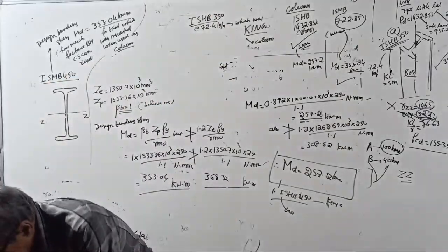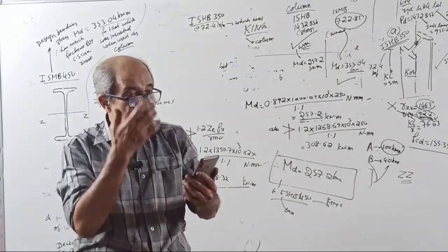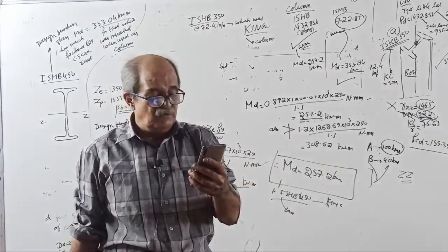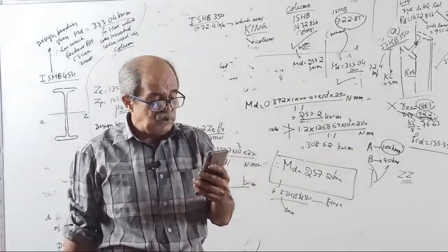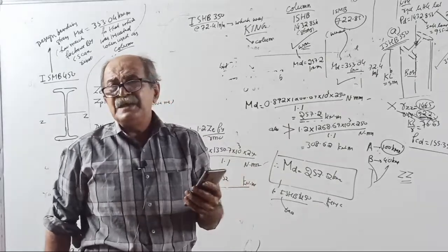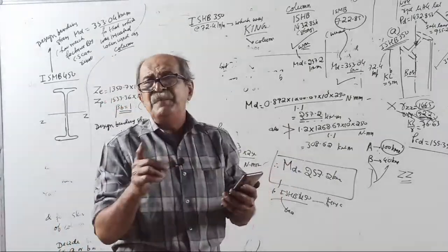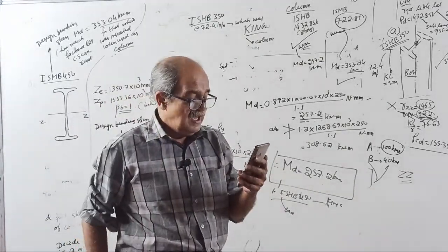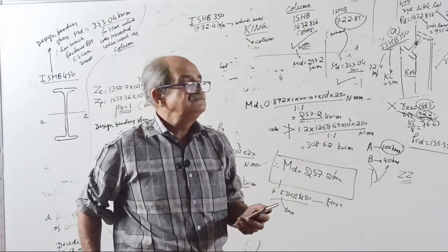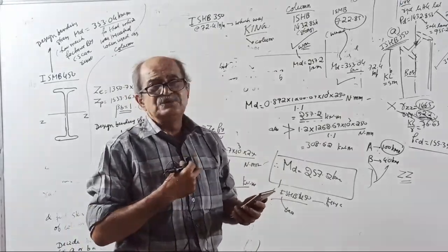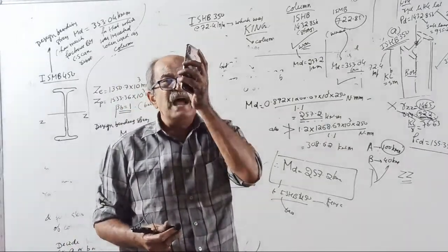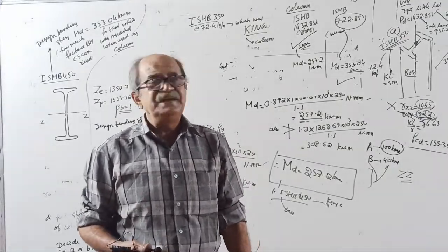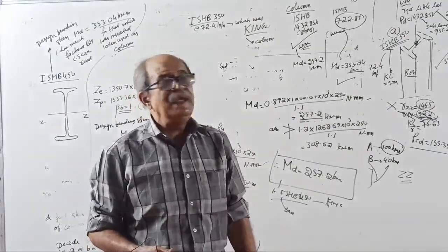Tell me, as a column, which is stronger, HB or MB? Same cost, everything is same. As a column, HB is stronger. But as a beam, the principle will be covered later in the beams. Today you believe me. As a beam, MB is the king. Clear? So practically also, for a column the most ideal RSJ is ISHB. For a beam the most ideal RSJ is ISMB.